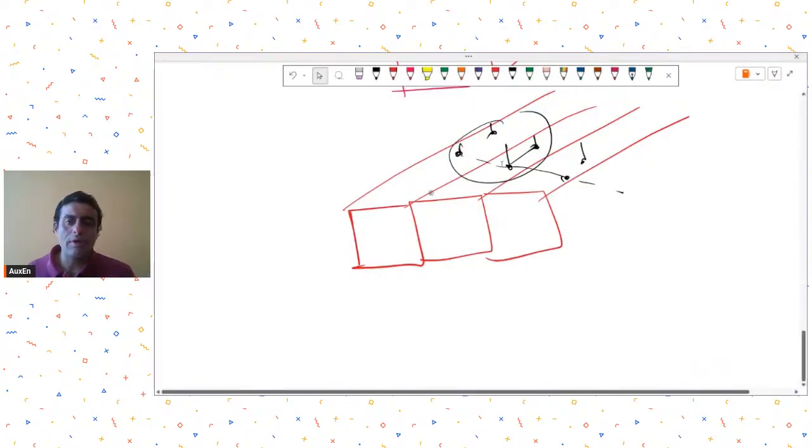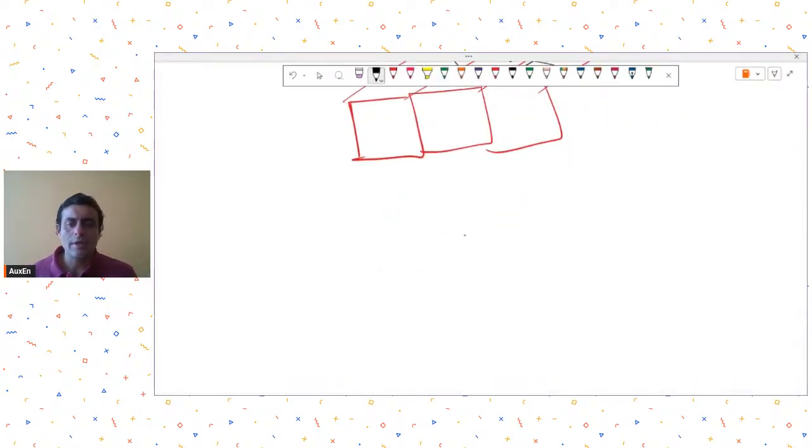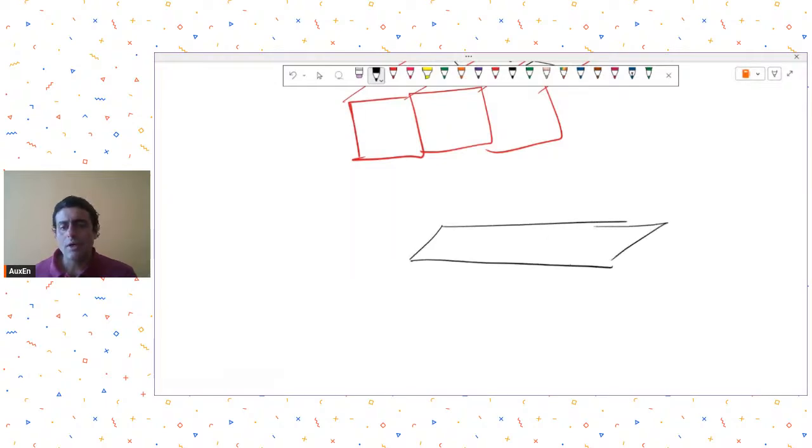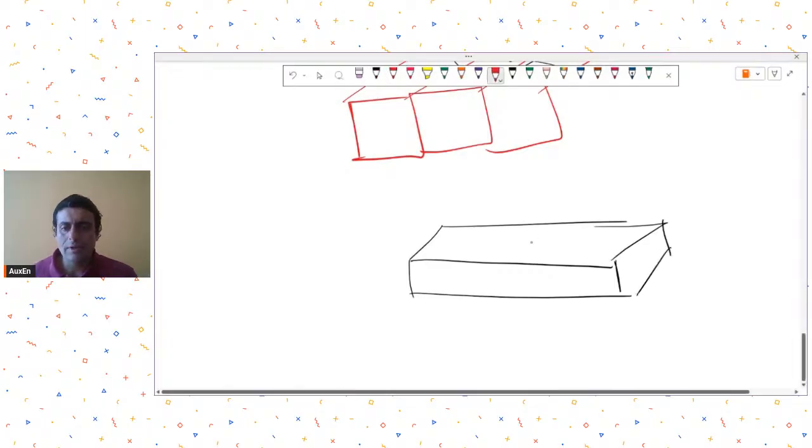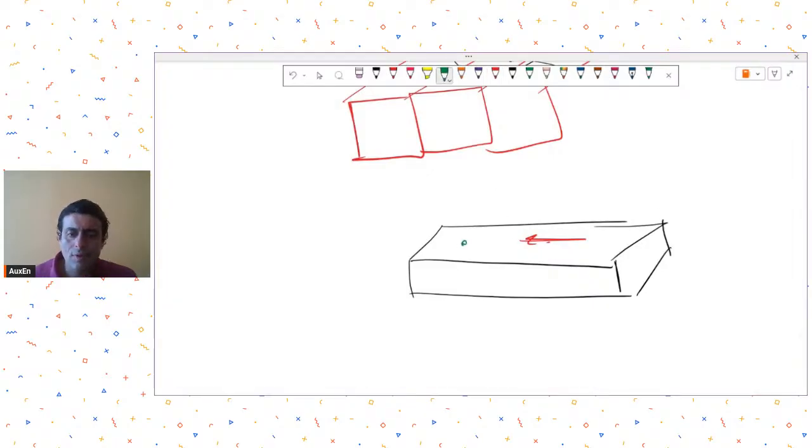Now, although it's quite rare, there might be a situation where your traffic direction is moving along the length of the box culvert. Although it's very rare that this will happen, let's say your traffic direction is moving in this direction. Then again you may see how many axles can be there on the length, and accordingly you can take the point loads. Okay.